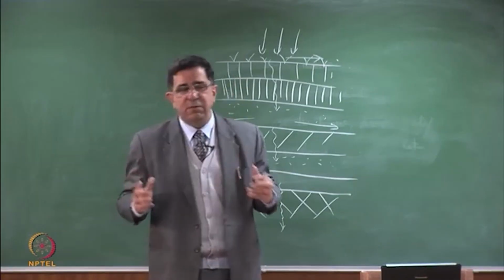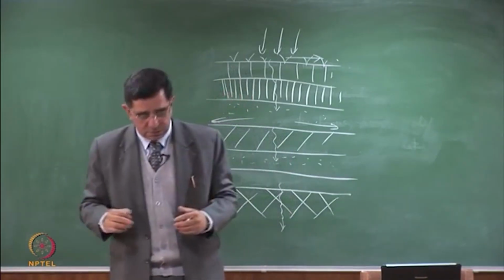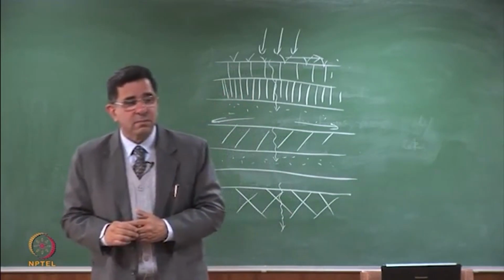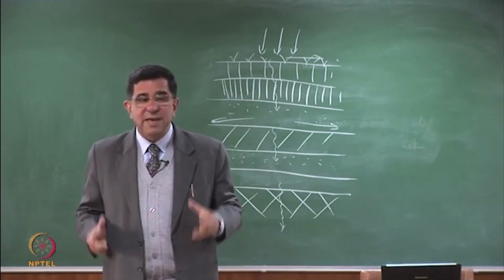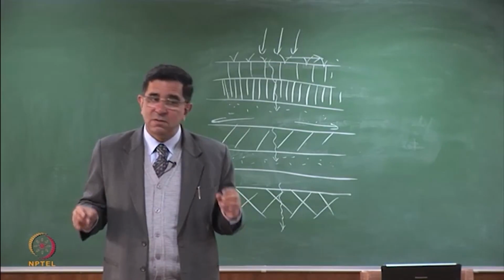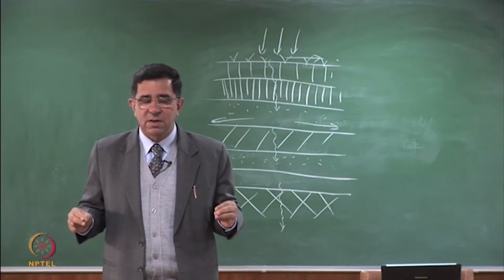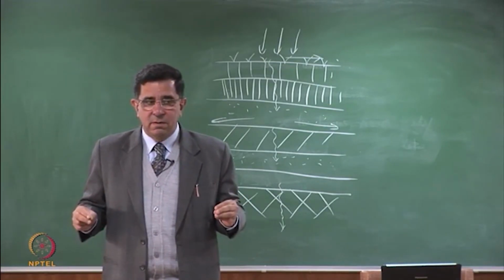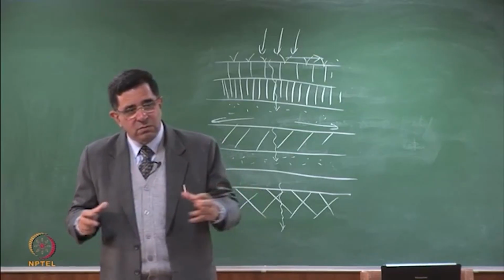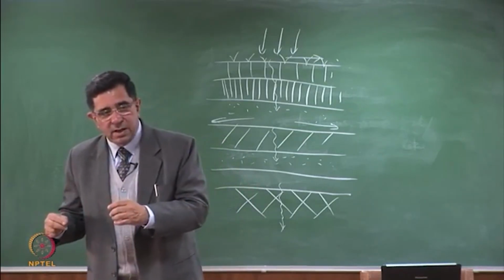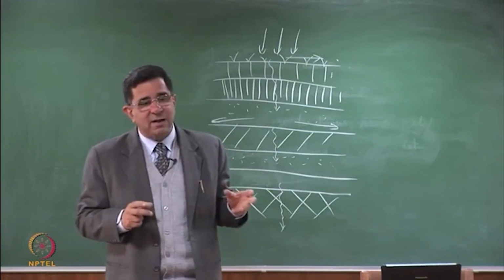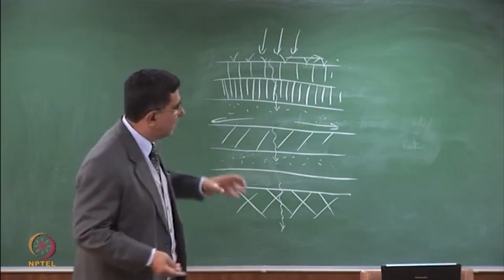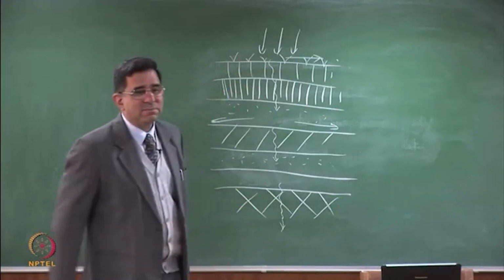Where is the leachate coming from in a landfill? The bulk of the leachate comes from the active phase. This is what you have to fundamentally understand. If I am taking out 100 units of leachate every day, the bulk of the leachate in that 100 units is from the active phase. Why? Because in the active phase this cover doesn't exist.